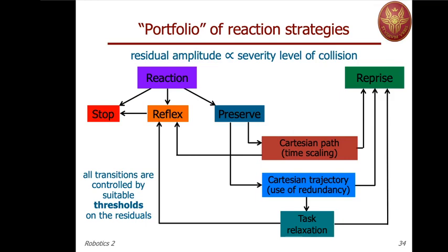For instance, you can abandon the specification on orientation and preserve only the position. If everything goes well, so that the collision is surpassed, then you can resume the original task, maybe compensating for what you have lost. In case the task relaxation is not enough, then again you return to the basic reflex reaction and eventually stop.